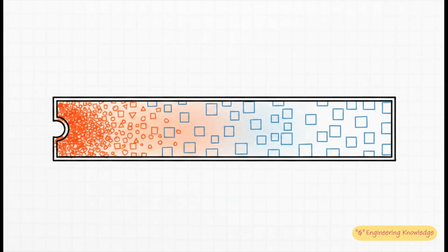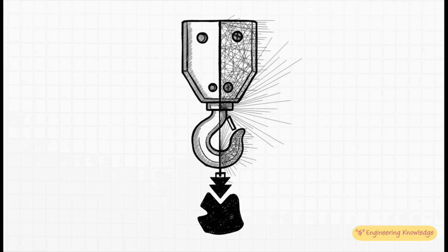So how do we speed things up without compromising the data? We rely on a really beautiful piece of physics called St. Venant's principle. This principle essentially tells us that local stresses in one region don't deeply affect the stresses far away from them. This is huge because it allows analysts to smartly refine the mesh into tiny elements only in those critical high stress areas, while safely using much larger, computationally cheaper elements everywhere else. It literally saves hours of computing time while keeping the fidelity incredibly high. And honestly, when this is done properly, the results are just deeply satisfying.